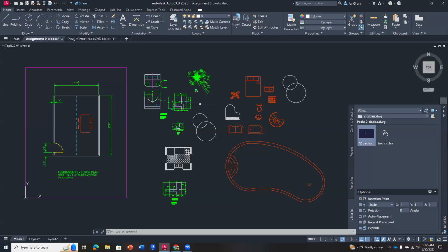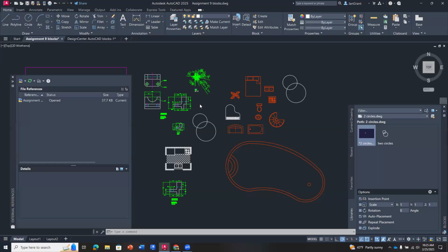files to it. If I think about a ceiling, I can work on the ceiling pattern and I can reference the electrical, reference the mechanical, reference whatever, structural. And all of those files are all working together, but none of them are inside of each other, but I can still see it. So I would type in XREF, and this is a different dialog box.